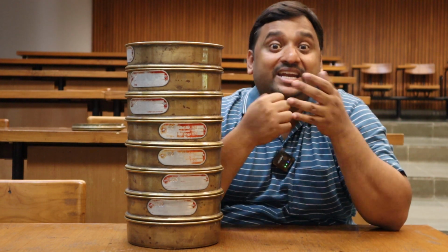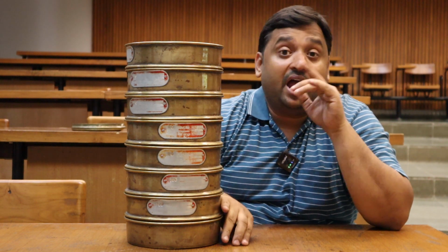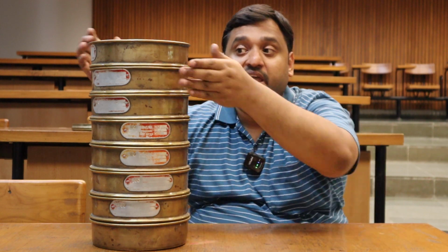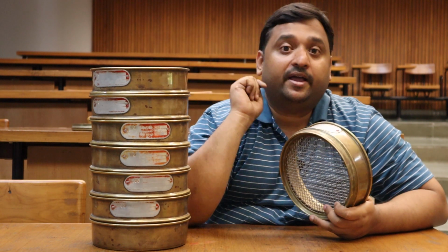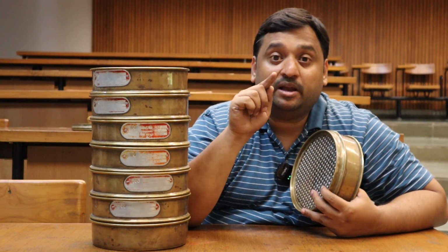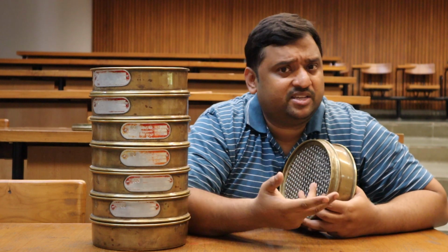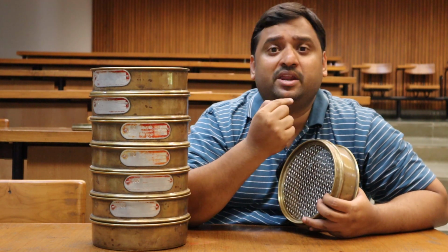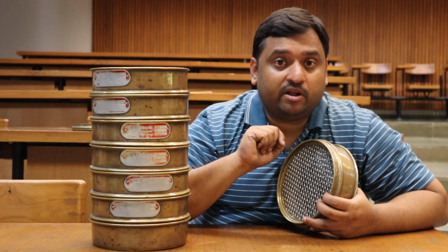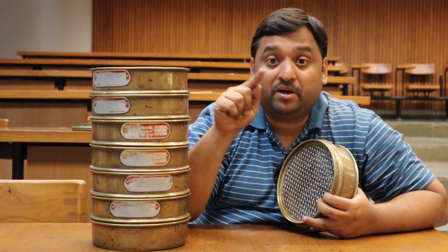Once I go to the Indian standards, they define the mesh number in a different way. And in Europe, or in countries like South Africa, they use a different kind of mesh number. For example, sometimes the mesh number is in terms of per square inch. Till now we have discussed the linear inch. What is the square inch? Mesh number 4, as per the South African standards, is 4 per square inch.